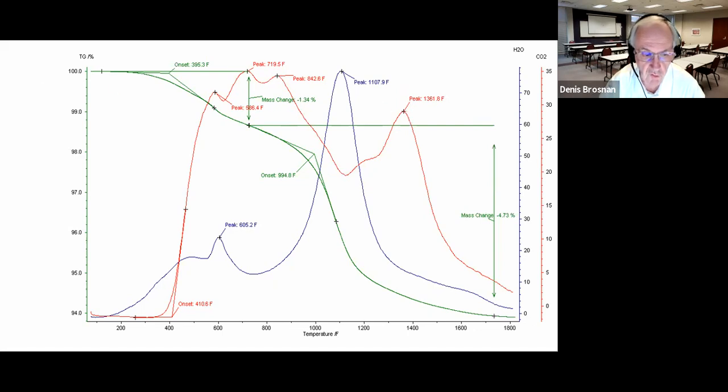So I hope that you can see that these types of graphs are very useful. Laboratory data is very useful for you to understand what's happening in preheat. So if you're not interested in heavy clay products and you're making a technical ceramic that contains a complex polymeric binder, you want to look at how the binder is removed. Of course, complex polymers are removed by something called depolymerization.